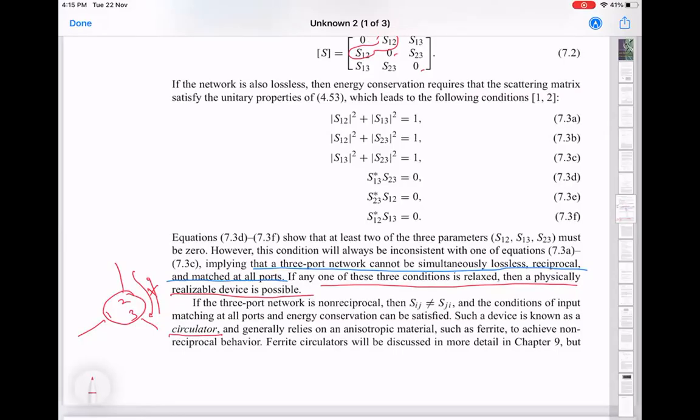So there was a requirement for doing these kinds of operations even on chip, integrated with the devices you are actually making. And the primary purposes of this kind of non-reciprocal thing are two. One, I showed you the reflection measurement, so for routing signals from in to out. And the second is actually for protecting your device from noise coming from further down the chain.